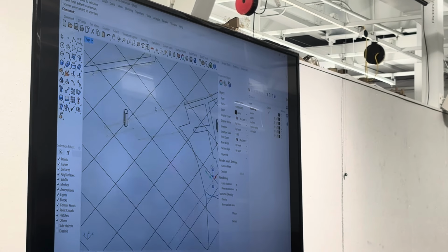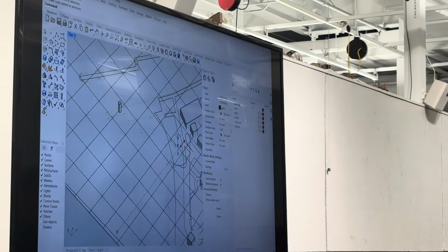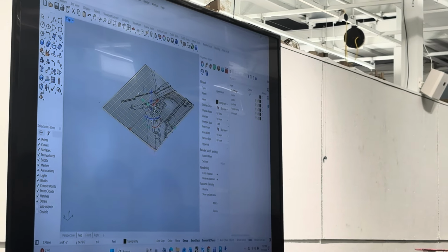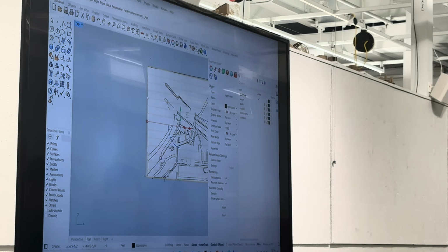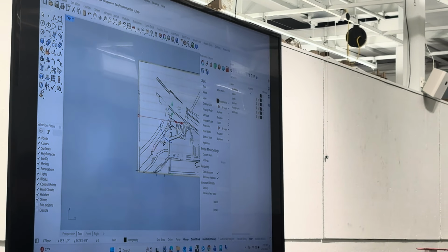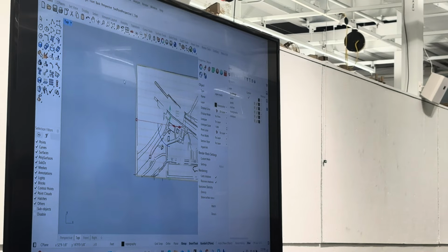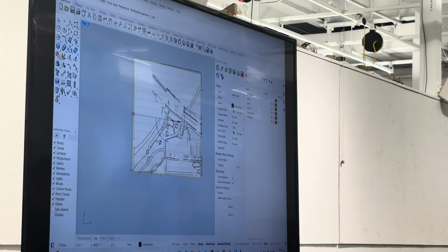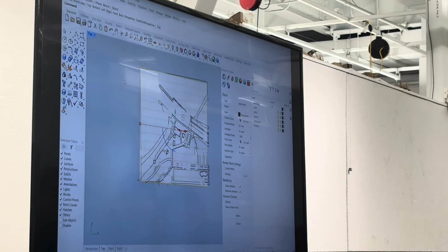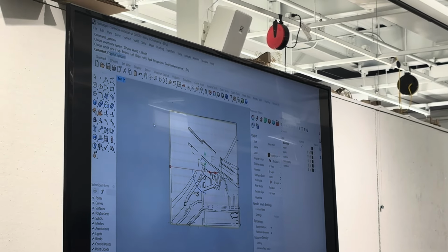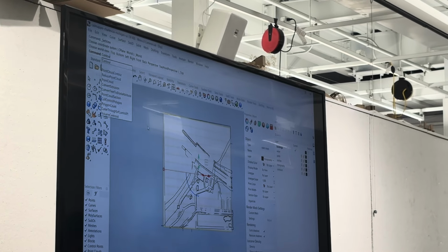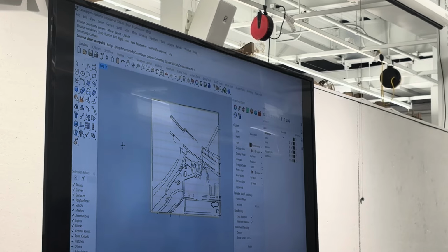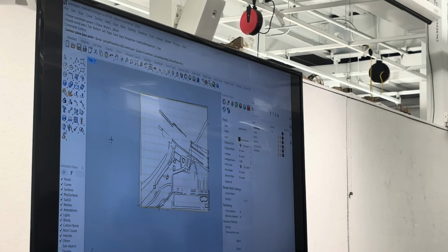So what we're going to do is just run the contour command. If you want to make contours and actually produce laser cuttable files, it's simple. Remember, anytime you think of a command, you think that you can do something to a piece of geometry, type it in, okay? So I want to make contours, what do I type? Contour, right? And here's where you would set the intervals at which you're going to cut your pieces.